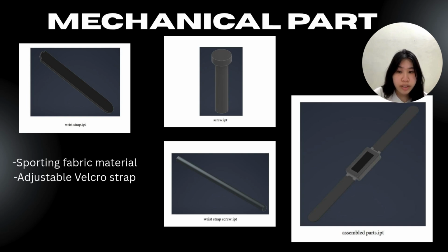After completing all individual components, the parts were combined in the Inventor assembly environment to create the complete mechanical structure. Assembly constraints such as mate and flush were applied to accurately position and align each component part, including the enclosure body, top cover, protective screen, and strap mechanism.